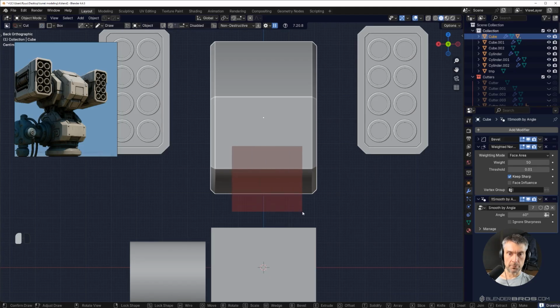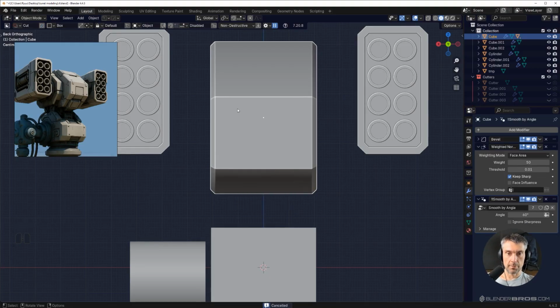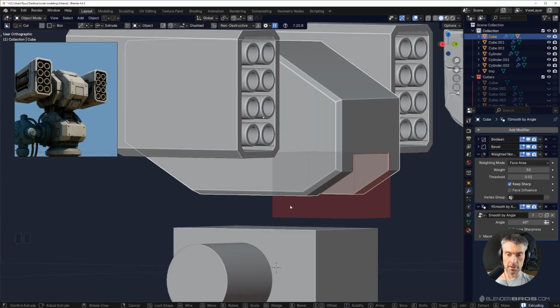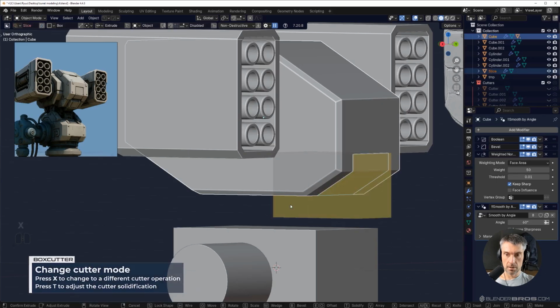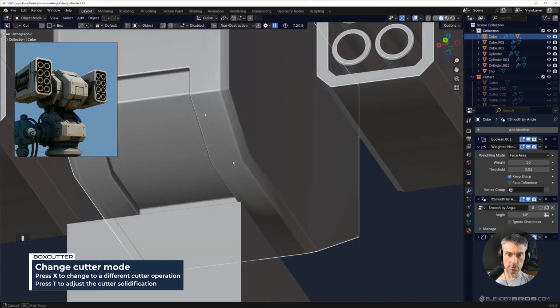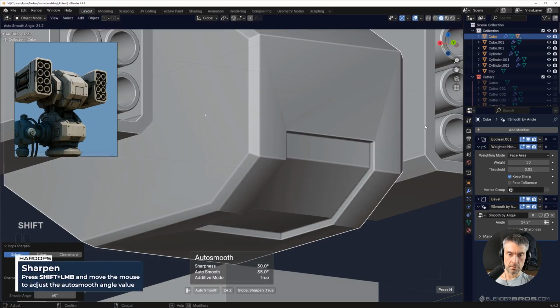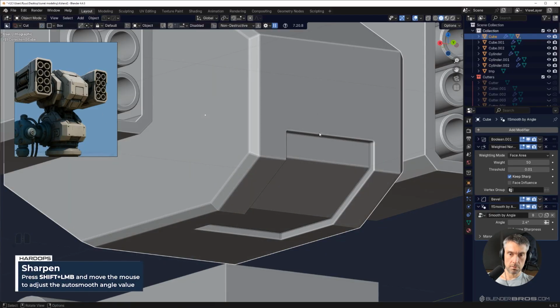If you run it from a lower perspective, it's going to be more aggressive. It's going to be like a low mouth. Because as humans, we always look for faces in shapes, a reflection of ourselves. So when you look at the trash can with the two openings and a gap, it looks like a human face, right? So if I run it higher, it's going to look less intimidating. If you run it lower, it's going to be way more intimidating. So I'm going to run it lower, and I'm going to run an inset cut. So inset boolean, tap X a few times to access the inset boolean, press T to adjust the thickness of the solidification. Here we need to fix this angle a bit. There we go. That's better.